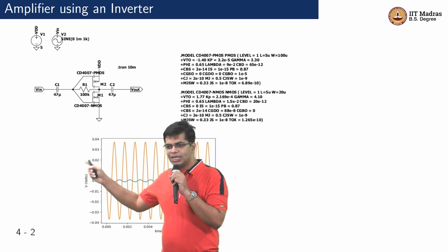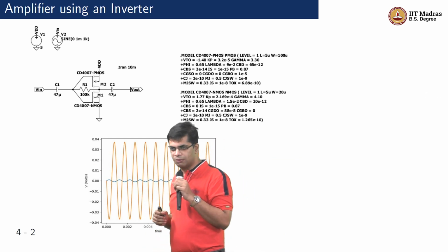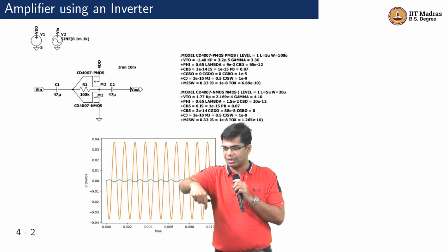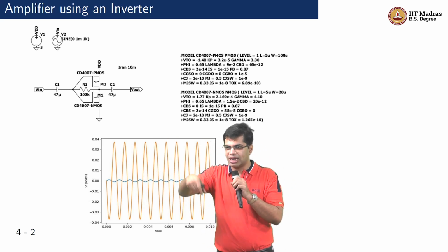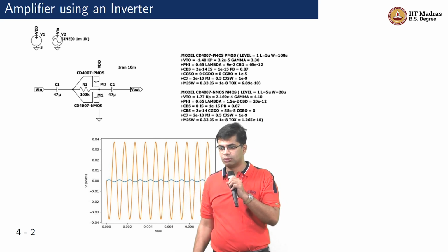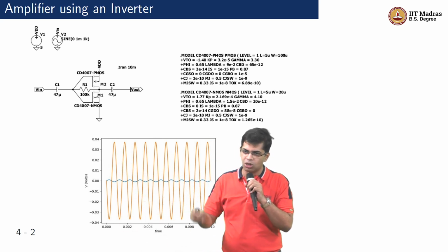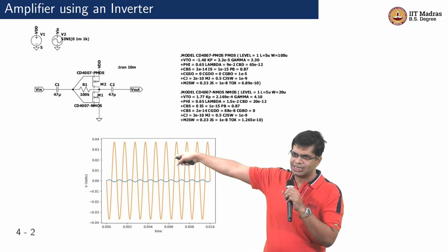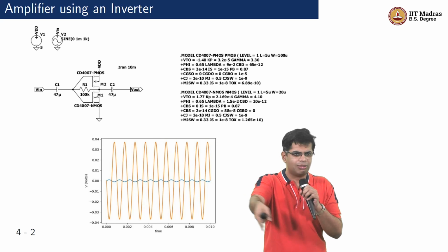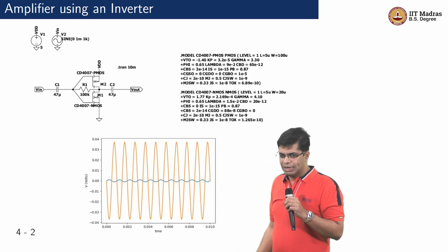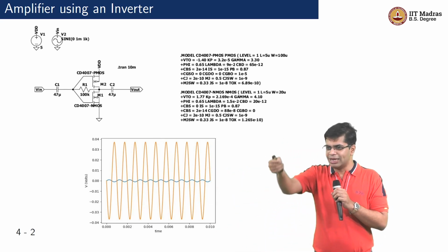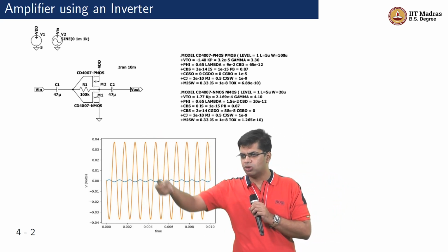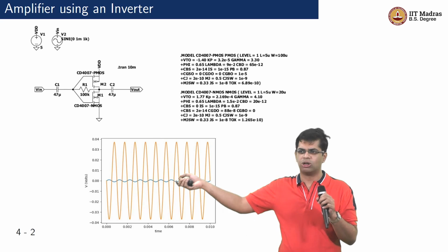Then one challenge in any such amplifier is the following. If I take out this particular IC and stick a different IC, same number, but a different IC, the gain will change. Because the gain in this depends on what's called the transconductance, gm, of the specific transistors inside. And if I take all resistors of 10K, if I measure, one of them will be 9.9, another will be 10.2. So depending on that variation, my gain also will change.